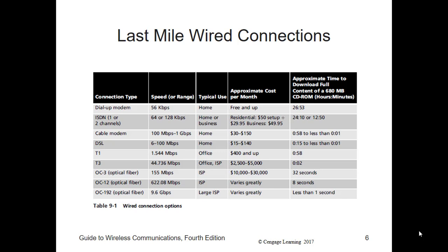Like for long distance connections between cities and states, copper-based digital communications such as a T1 line required the signal be regenerated every 6,000 feet or 1.8 kilometers. In addition to the challenges of cable installation and maintenance, regenerating the signal requires electrical power at each repeater location. Maintenance cost for this type of connection is high, especially when the geography and environmental conditions might be challenging.